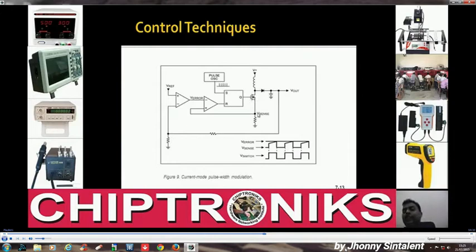External MOSFET. In all the examples I'm showing, those are all asynchronous switching regulators. Asynchronous switching regulator means there is only one MOSFET used and another is a diode, whereas in a notebook motherboard, synchronous switching regulators are used, and they are better. We will discuss why synchronous switching regulators are better. Why I'm discussing all these things is to understand switching regulators in a better way.